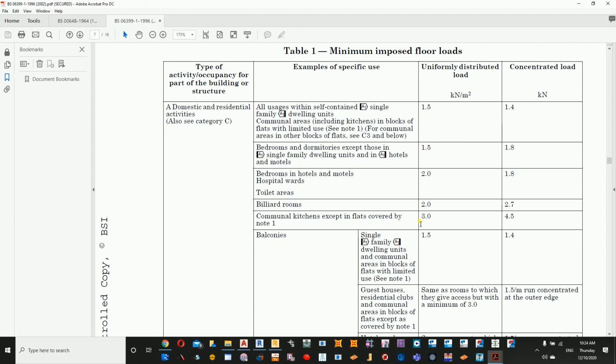But here in Oman, we don't normally have separate live loads. We don't use separate live loads for the different functions of rooms. We take only one for the whole floor, which is normally the higher side. You check whatever the functions are, and take the higher side. As I told you, a room might be shifted to become a store because nobody is there now. So you need to take that into account, because a bedroom or a room is going to have less load compared to a store. So I should be designing it for something higher. All of them for the higher side, one value. This is what we normally do.